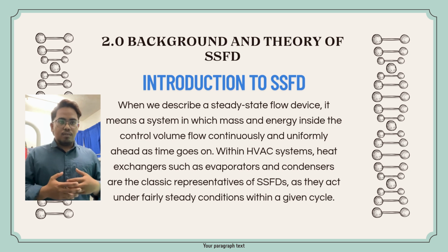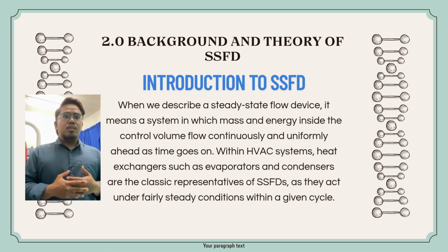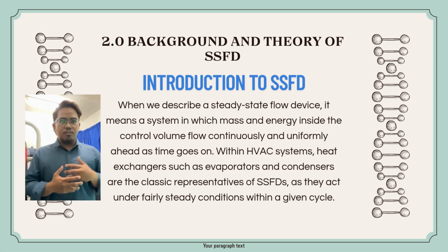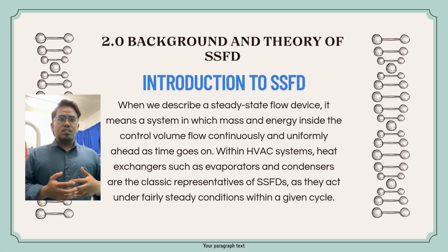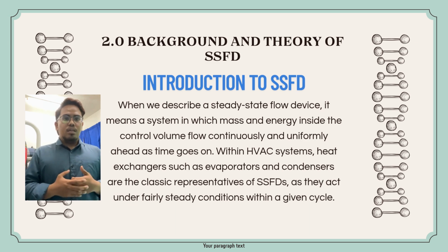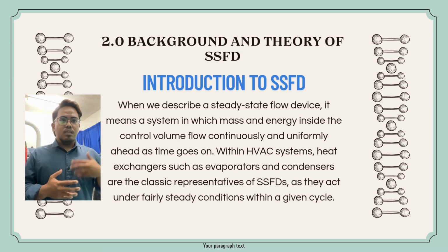Alright, so when we refer to a steady state flow device, or SSFD, we are talking about a system where mass and energy flow continuously and uniformly through the control volume over time. In other words, the system's condition remains stable during operation. In HVAC systems, classic examples of SSFDs are heat exchangers like evaporators and condensers. These components operate under relatively steady conditions within each refrigeration or cooling cycle, making them ideal representations of steady state flow behavior.